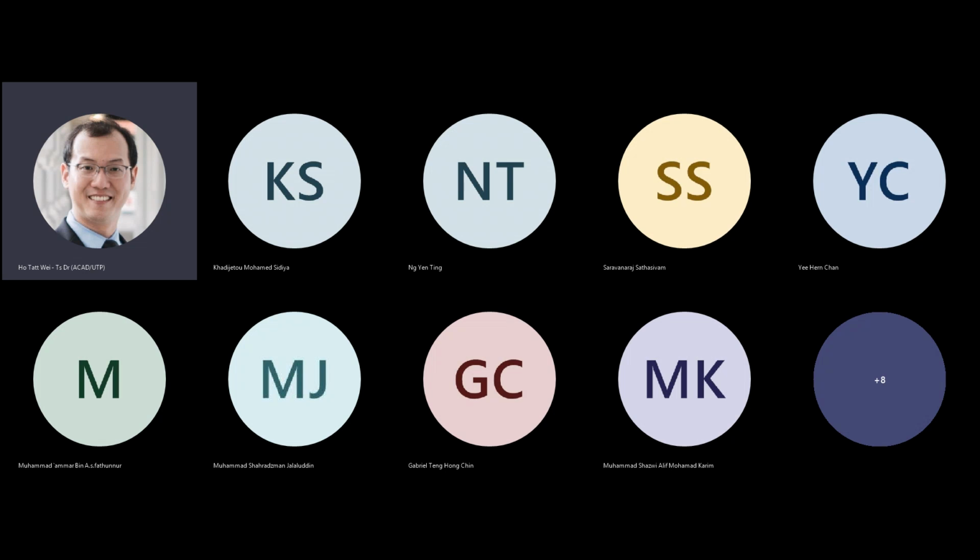We're going to be doing the analysis on the critical path, and process variations will introduce multiple near critical paths that may become the critical path after you do the fabrication, because you can't control with absolute certainty the device that you make.